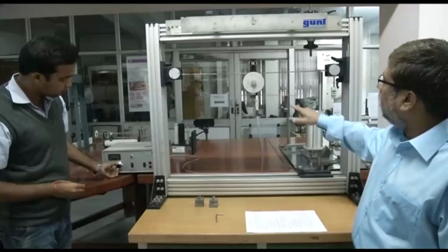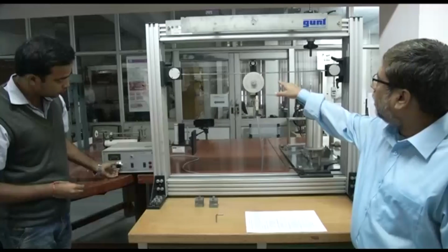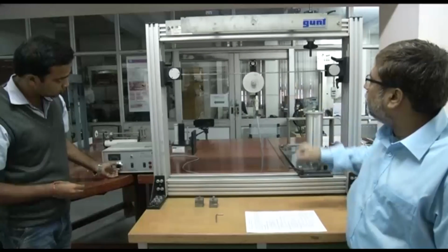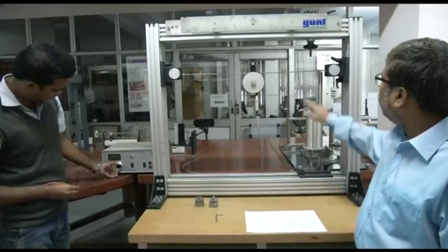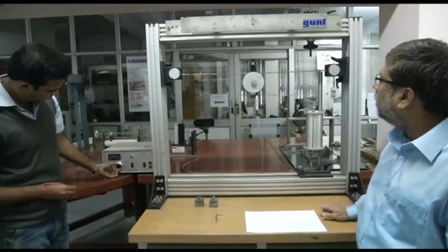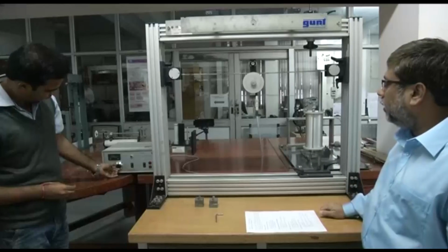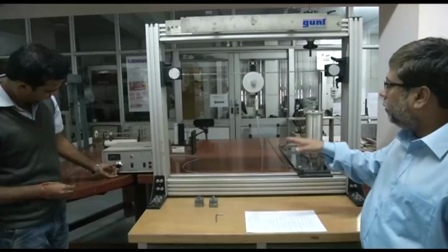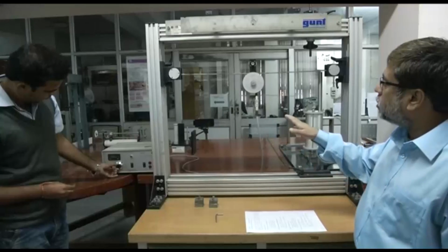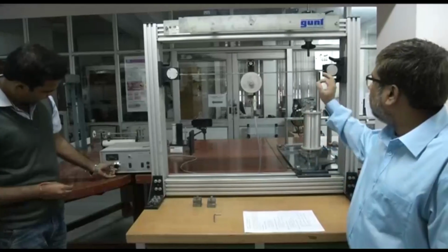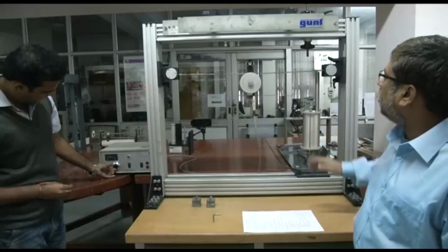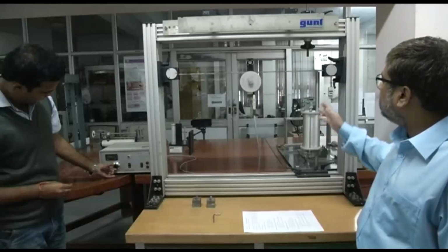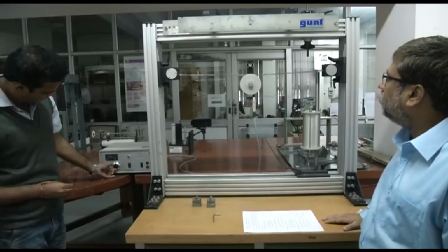As we can see here, this motor is actually giving an eccentric harmonic excitation to the system, and during that load we can see that the beam is getting gradually excited, and the frequency we are controlling from here, and we will be gradually reaching a frequency which is close to 7 Hz. 7 Hz is the first natural frequency, or fundamental frequency, of this system, where we will see that the resonance will happen.